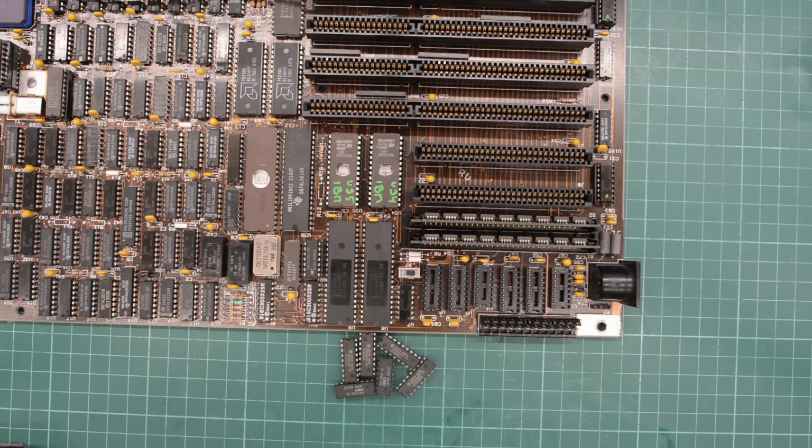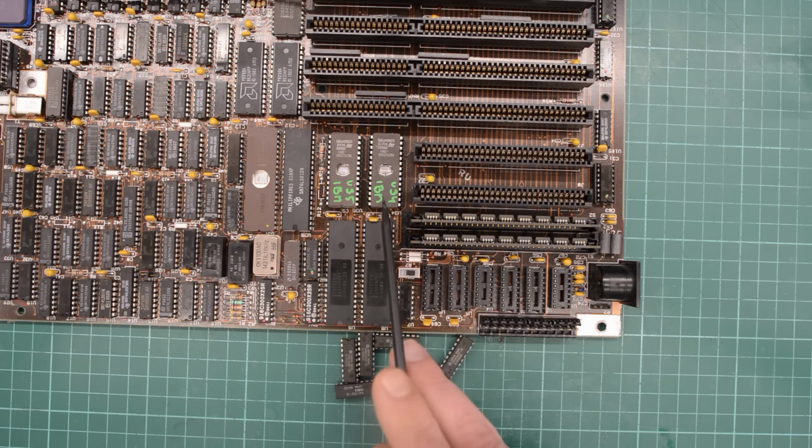Okay, here's my next theory. According to the POST code, we could get this error if the board is trying to check a different size of RAM than it actually has. I don't know what the default value in the BIOS is, but what if these machines were sold with 640K standard? But we're only running 512K with these two SIMMs here. I have tried to boot this machine with this extra RAM on board, but what if one of these original chips is bad? Then the board still has less than 640K. And we obviously can't change those settings, because we can't boot from the setup disk.